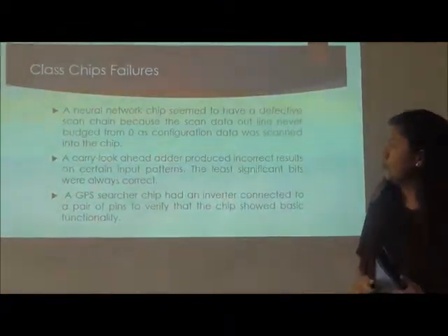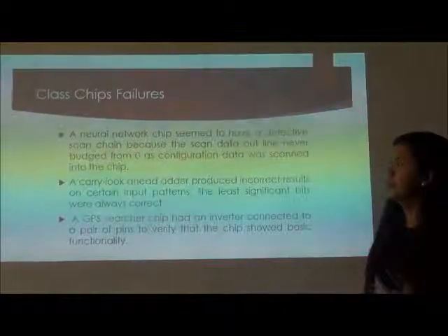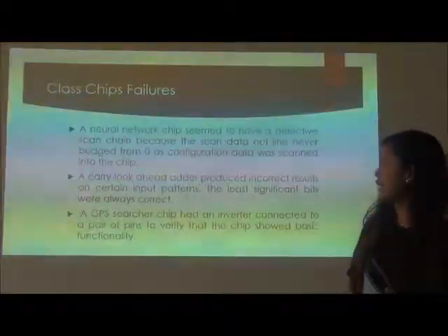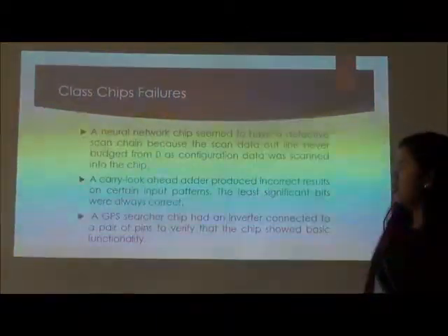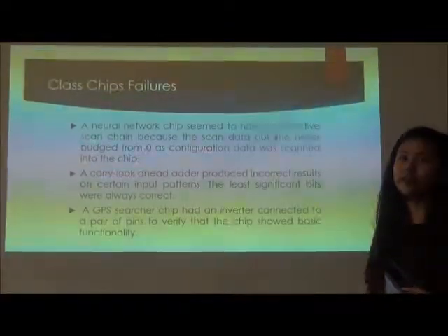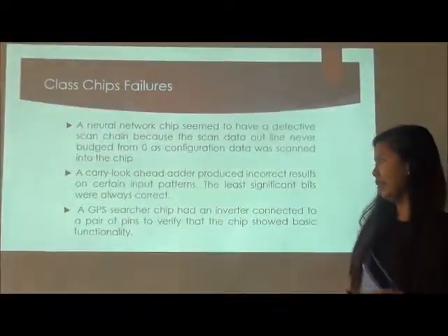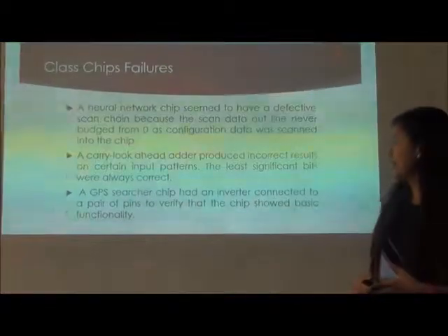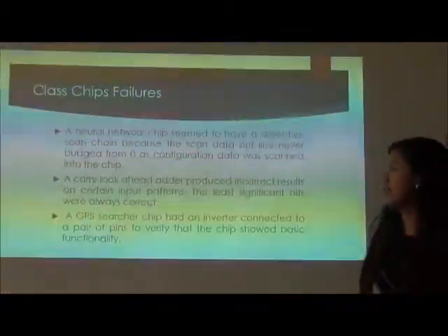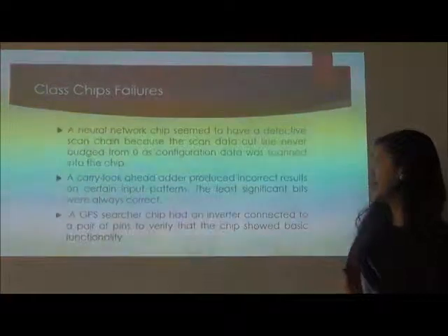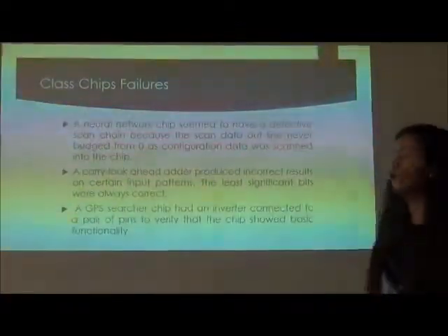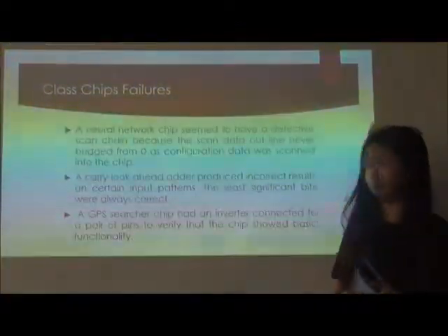A neural network chip seemed to have a defective scan chain because the scan data output never budged from 0 as configuration data was scanned into the chip. Then, a carry lookahead adder produced incorrect results on certain input patterns. The least significant bits were always correct.